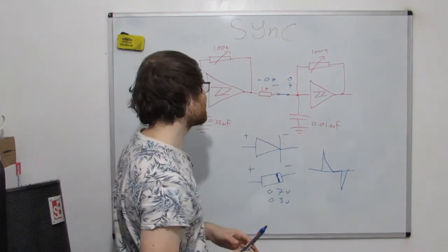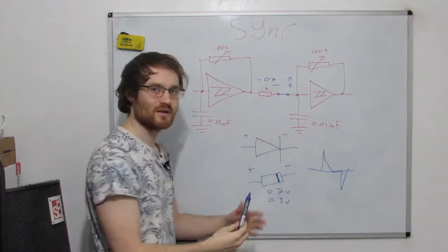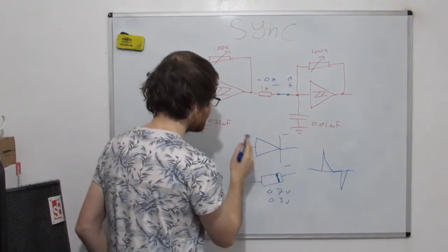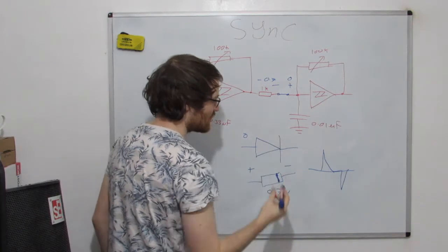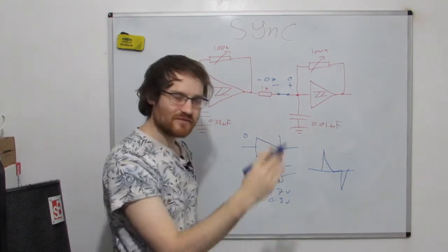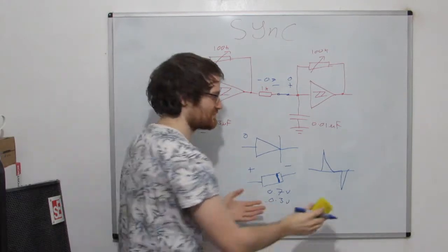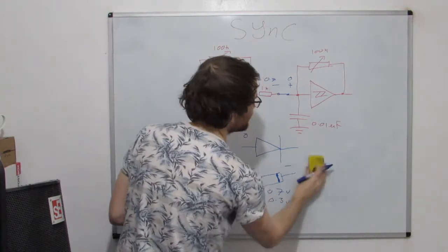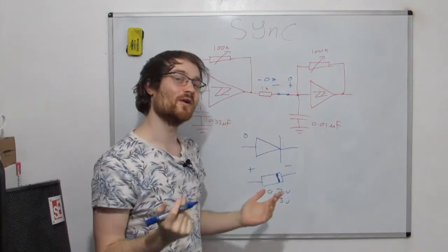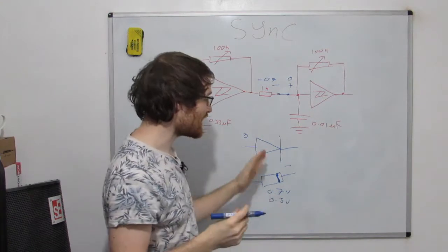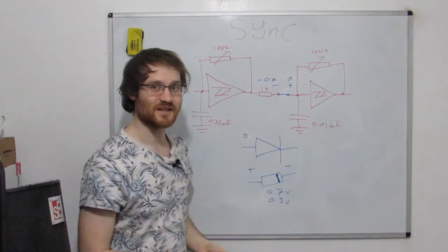The other thing about diodes is they will block current coming this way. So if this is ground, say, you can apply almost any voltage to this, 5, 10, 20, 50 volts. Eventually though, just like anything, they will break down. They've got some voltage where the voltage is high enough. Remember, voltage is a force. The force is high enough, there's enough potential energy here to just destroy the diode, basically.